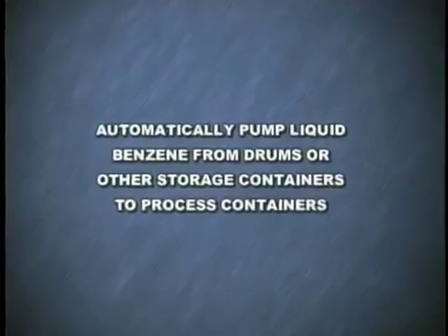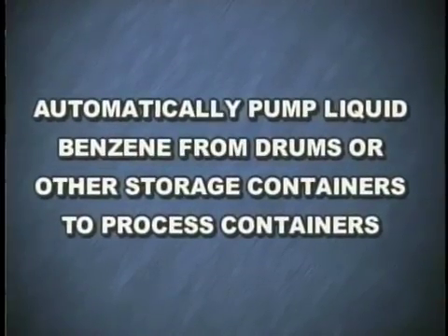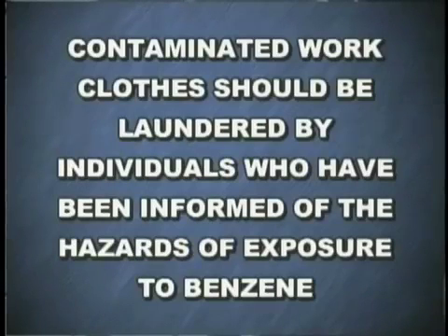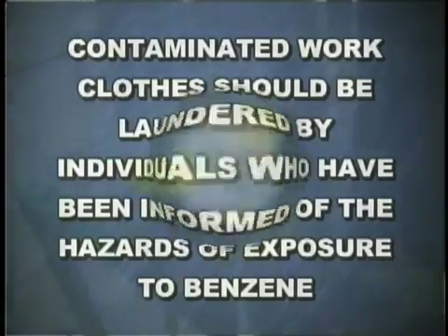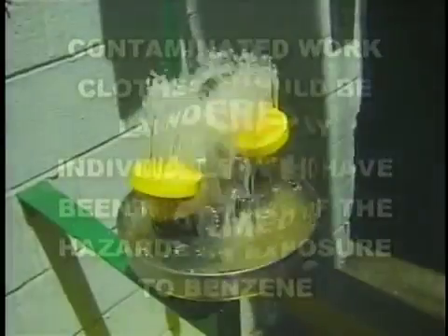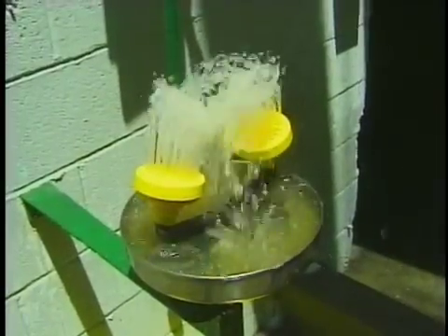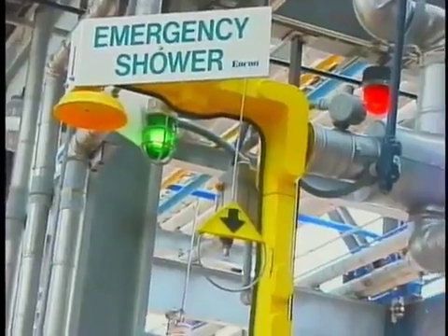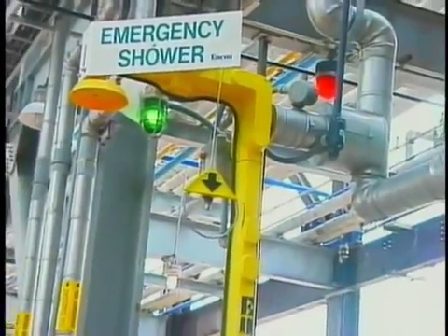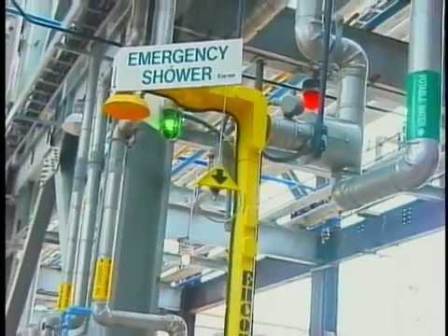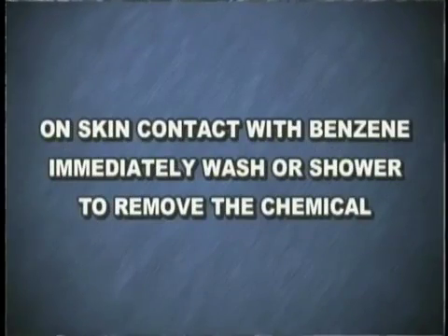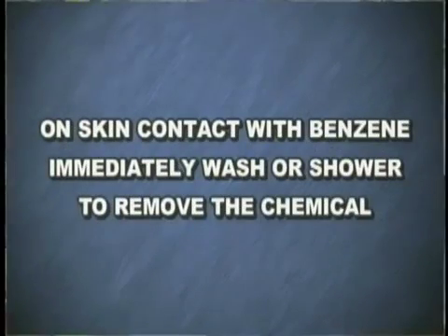Where possible, automatically pump liquid benzene from drums or other storage containers to process containers. Contaminated work clothes should be laundered by individuals who have been informed of the hazards of exposure to benzene. Eye wash fountains should be provided in the immediate work area for emergency use. If there is the possibility of skin exposure, emergency shower facilities should be provided. On skin contact with benzene, immediately wash or shower to remove the chemical.